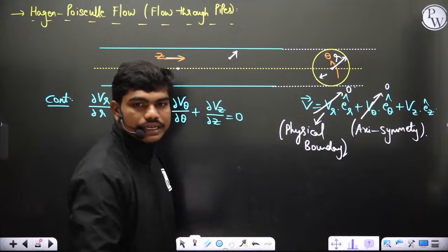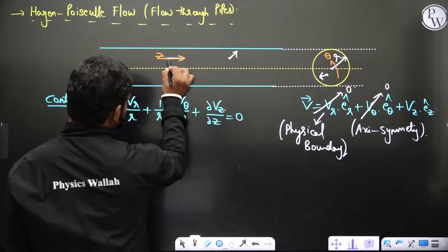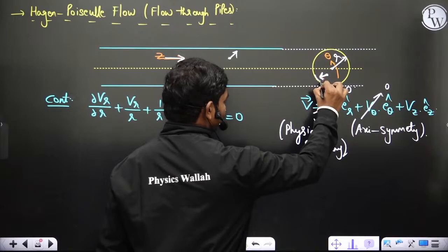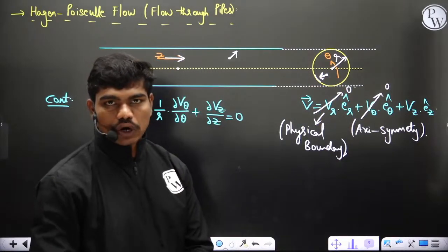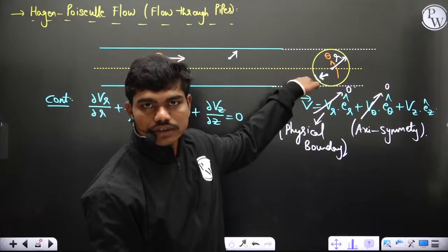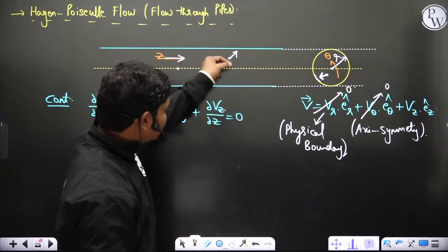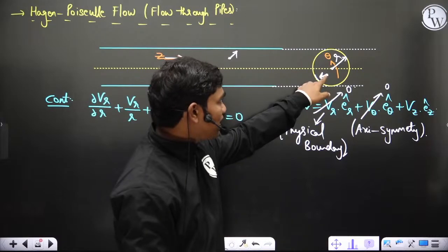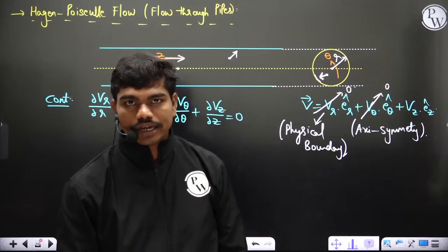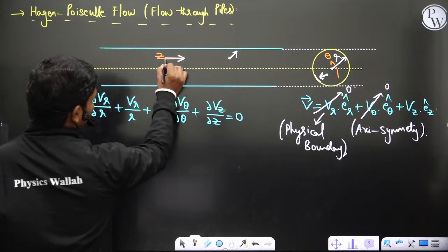See, what we are doing is, if this particle tries to deviate from this motion and achieve this other motion, which in the side view is the particle moving radially, very soon it will get in contact with the pipe wall, and within a very short time the radial component of velocity becomes 0, because the particle cannot move further, so it gets restricted. Similarly, we are also assuming the particle will not rotate about the axis of the pipe. In the side view, this particle will only travel straight in the z direction. So these are the assumptions. Therefore, these two are zero, and you have only Vz, which is the flow velocity in this direction.